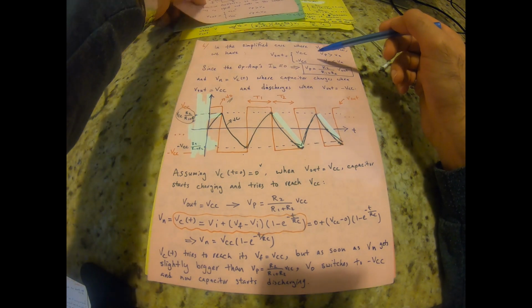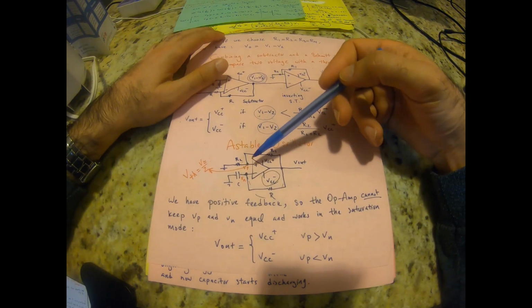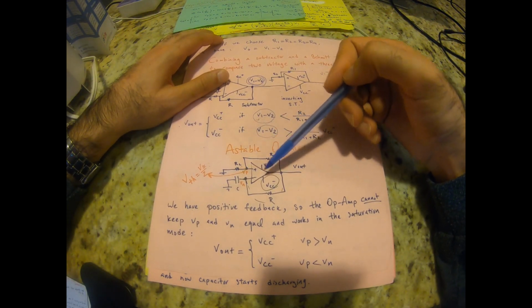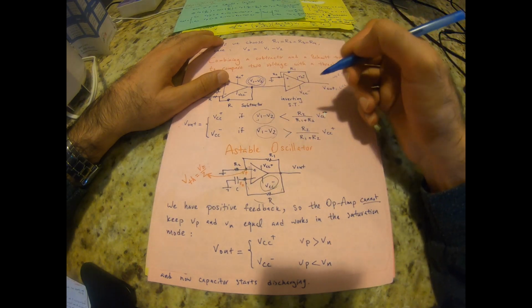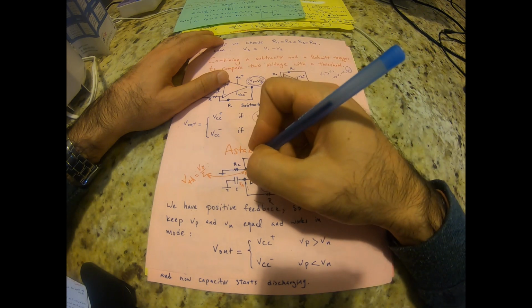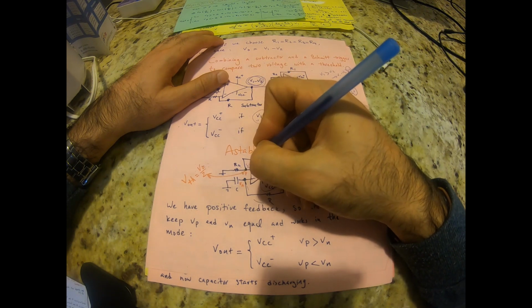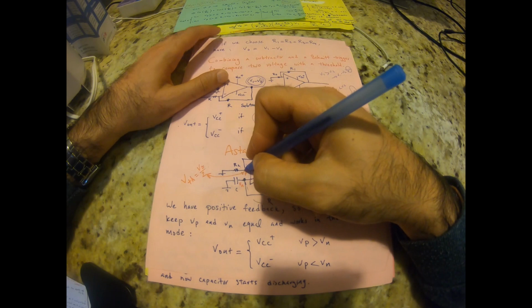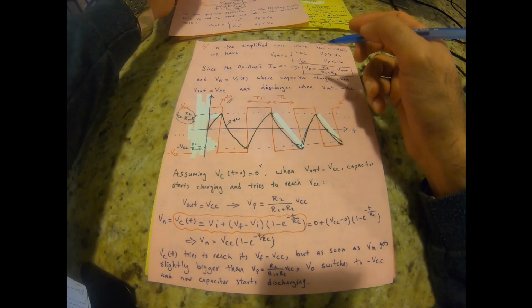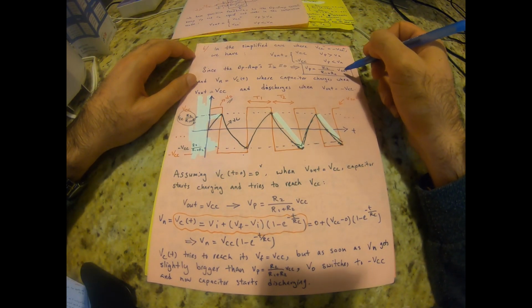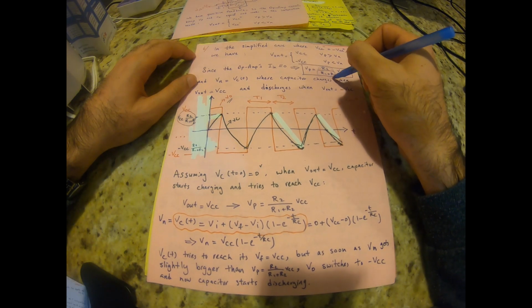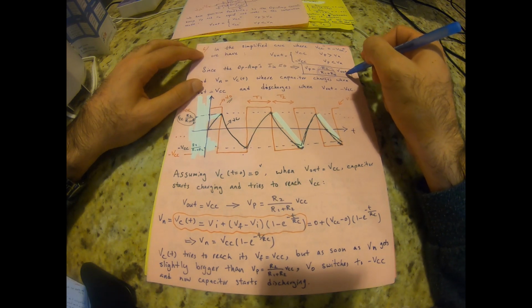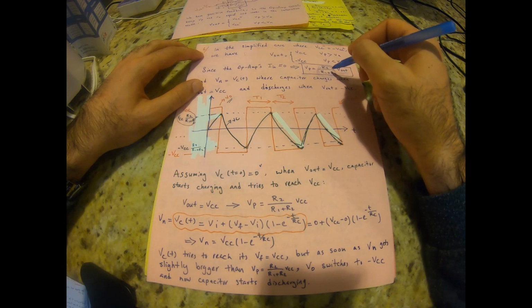Now let's look at the circuit one more time. In the positive feedback, we just have a voltage divider because there's no input going into the op-amp; I in of the op-amp is almost 0. So here VP is basically R2 divided by R1 plus R2 times V out. So it's going to be either positive VCC or negative VCC times this term.